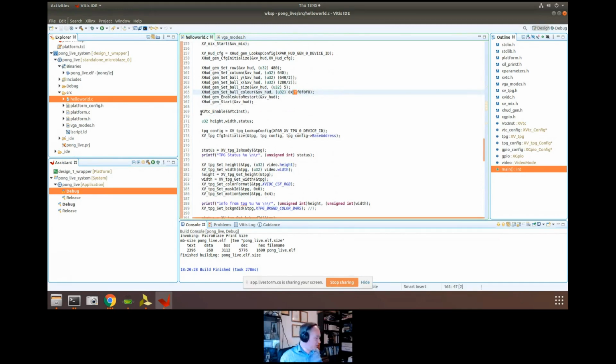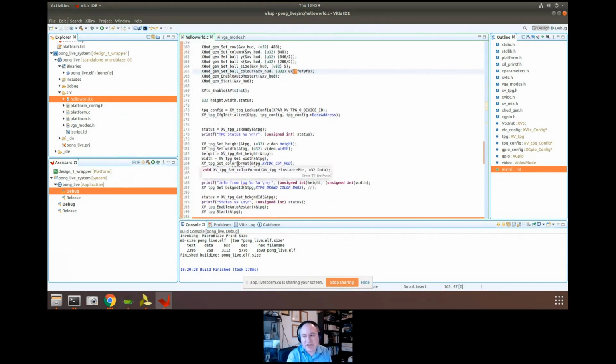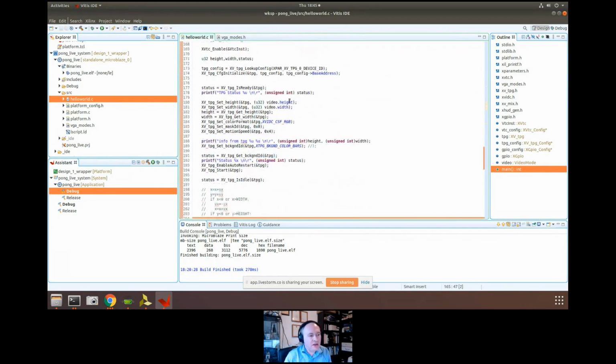Once we've started running, we come into the VTC, and we finally start the generation of the test pattern video. I'm just trying to look where we are in the notes at the moment. So we finally start the generation of the test pattern video. Once we get the test pattern video up and running, we're setting this again to be the video height, the video width, and we're setting the color format to be RGB because that's what we want.